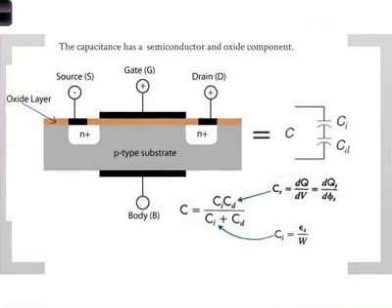Now, of course, that also means, because now you have voltage-inducing charges, that means you have a capacitance. Like I said before, that's your input capacitance, which is part of your input impedance, and you need to be able to account for it. Okay, so we have our familiar device, and the capacitance model is very straightforward. It's easy to understand too. Okay, so again, the device has an oxide here, an insulator, and you have a semiconductor.